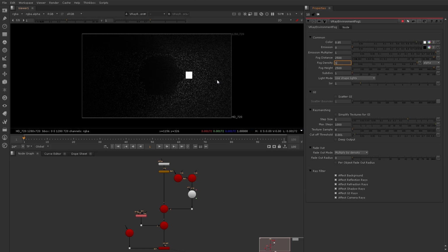So we need to find the right balance here. The fog distance means the wall of the fog is like the maximum; you cannot see past this wall. The fog density is how thick this wall is. If you keep increasing the fog distance, you'll get to see more of the environment. But if you bring it a lot closer, which previously was a value of 10, it means at a certain point in space you're no longer able to see the geometries and it's very, very foggy.